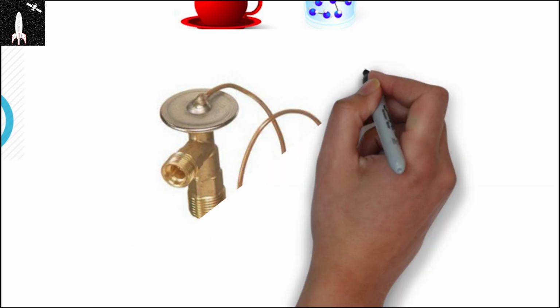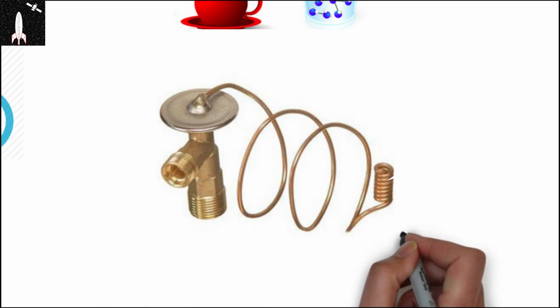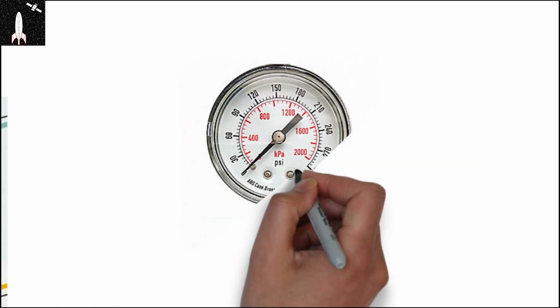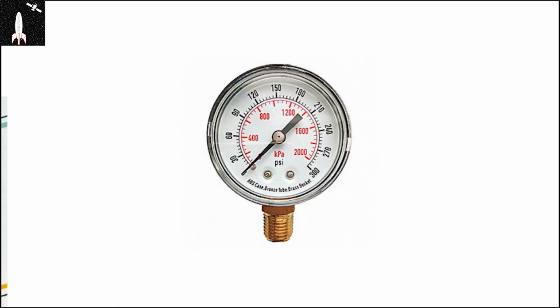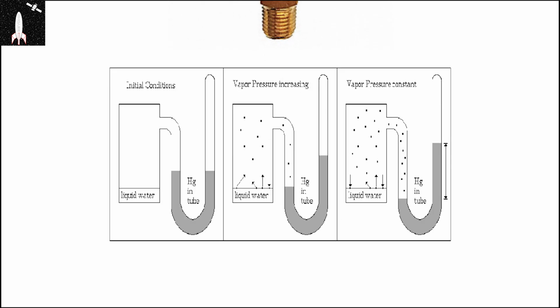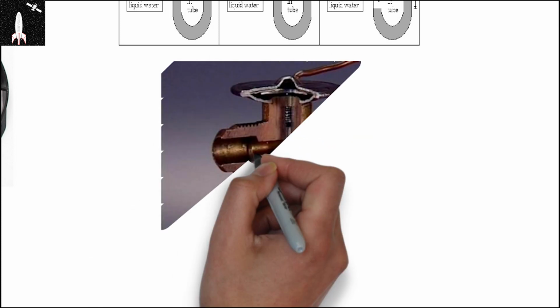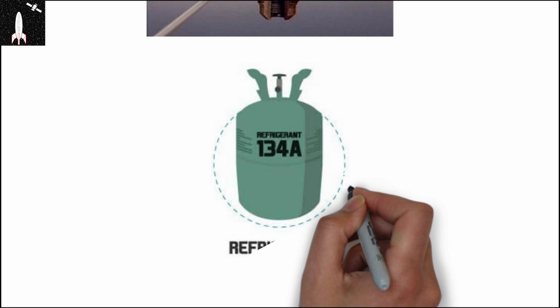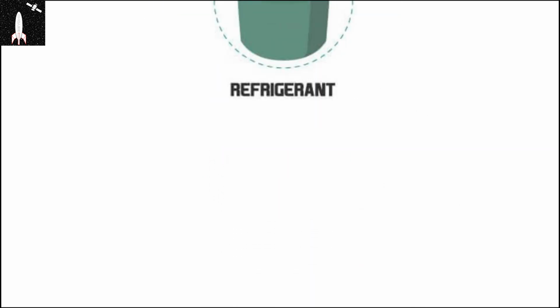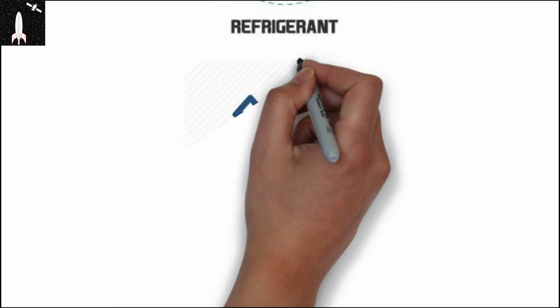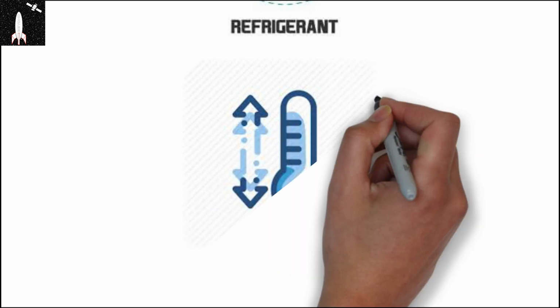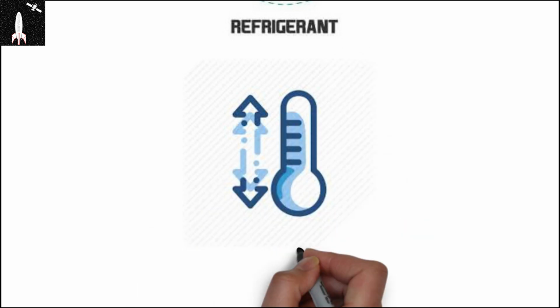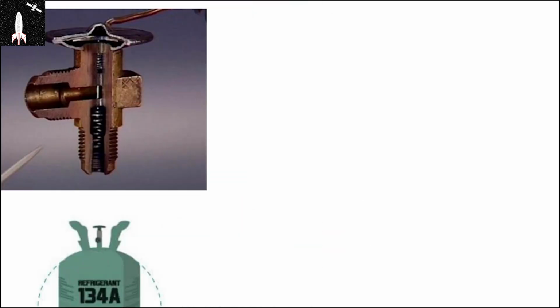An expansion valve is fitted at the exit of the condenser, which helps to restrict the refrigerant flow, which in turn reduces the pressure of the fluid. We may know that it is possible to boil a liquid just by reducing the pressure around it. This happens inside the expansion valve. When the pressure drops, one part of the refrigerant liquid gets evaporated. For this to happen, energy is taken from within the refrigerant, due to which the temperature drops. This helps to produce cold refrigerant inside the AC.